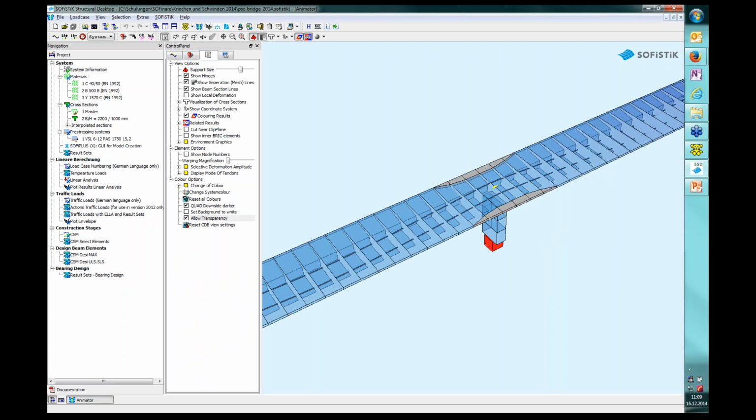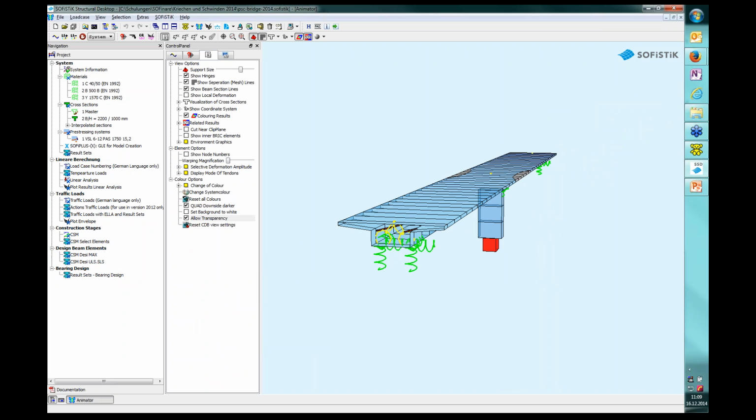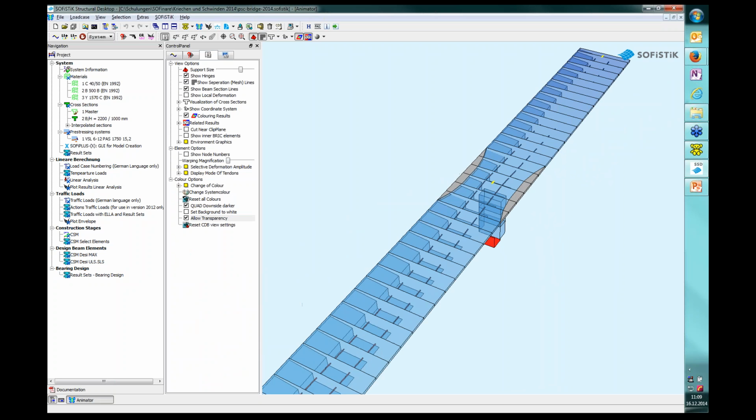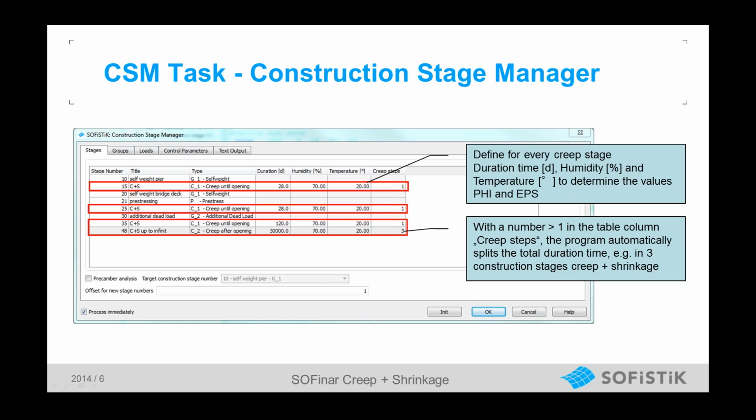You will see inside the system, and if I zoom in, you will see that we're dealing with two cables or two tendons on both sides of our web, and we have a standard T-shaped beam cross-section here. That's all we want to go for. The gray area you see here represents non-effective parts in the cross-section. So it's a very pure and very easy standard element.